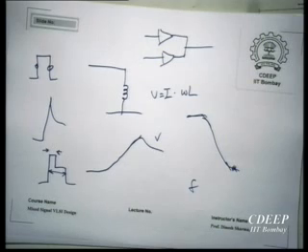It turns out that when you have equalized, you have equalized. So if you have a properly designed transmitter, then an inductive drive doesn't do too much. And when you have a properly designed receiver and signal to noise is already good, then an overdrive doesn't do too much. Remember, you only want to equalize. If the high frequency boost is more than that, it doesn't help you too much at the frequency.